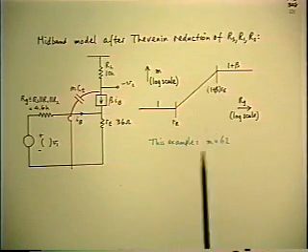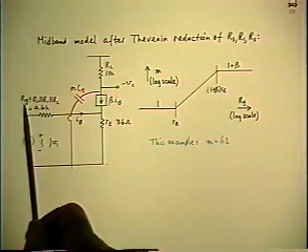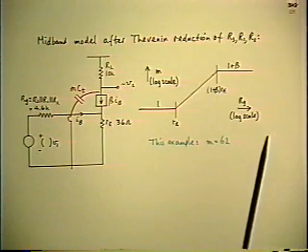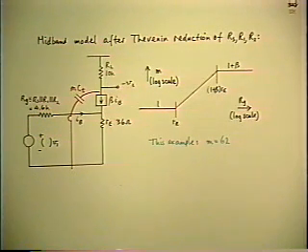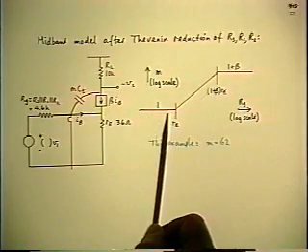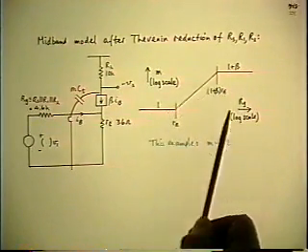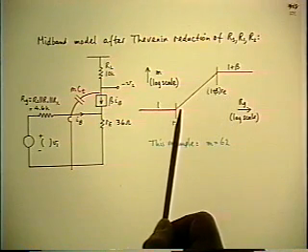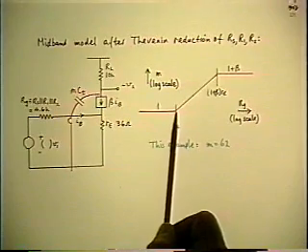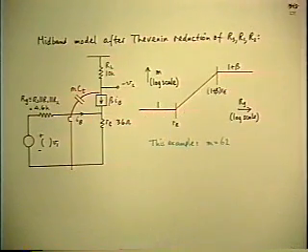What this tells you is, if you consider the RG as a design parameter that you have some control over, and you want to make a high bandwidth amplifier, then you want to keep the M low, so you want to be near the bottom end of the sketch. So you make the RG small. What this tells you is you can make it as small as about RE, and there's no further benefit in making it smaller than that.